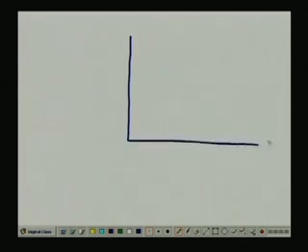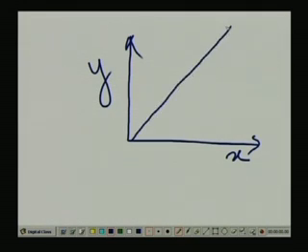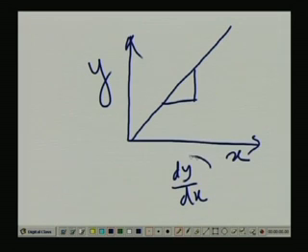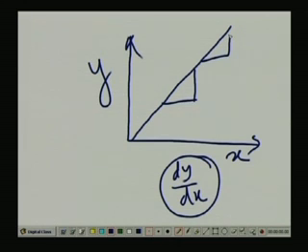Suppose I have this characteristic calibration curve, this is x, this is y, and I have a linear relation like this one. So, the slope of this calibration curve, that means dy by dx, will give you the static sensitivity, and since it is linear, anywhere the value of del y by del x is the same.